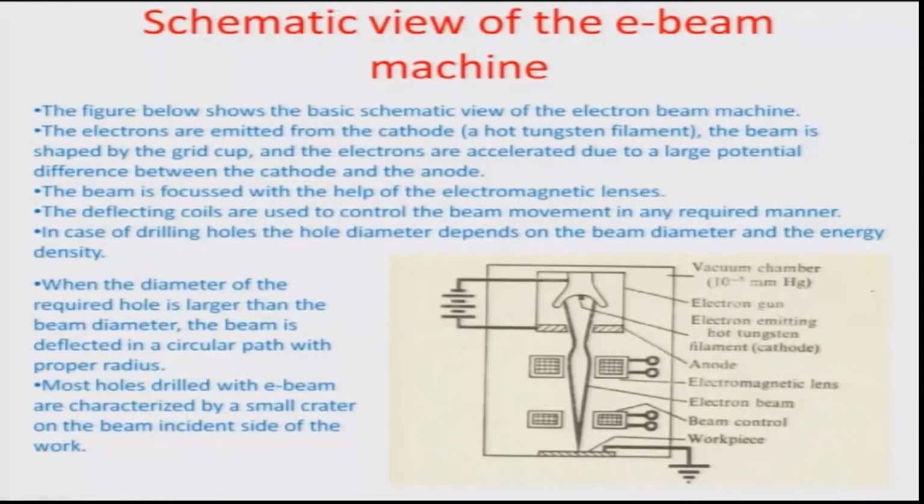Let us look at how e-beam is produced and what the basic principle of generating a fast moving electron beam is. It is basically the thermionic effect, and it starts with a hot tungsten filament. You have a hot, electron emitting tungsten gun or filament, which is the basis of starting the electrons, and then there is a series of perforated anodes, where there is quick acceleration of the electrons, and also some absorption which is generated.